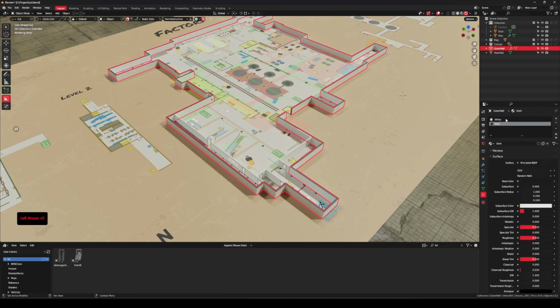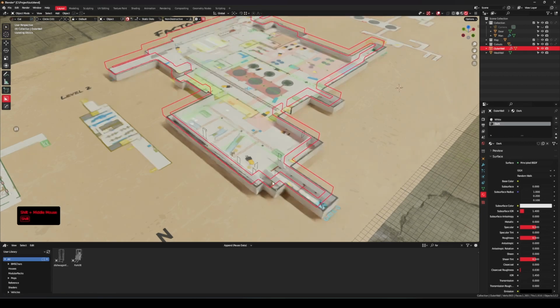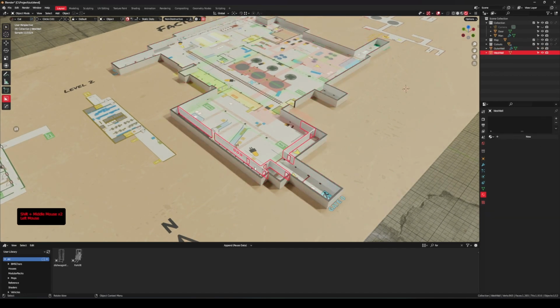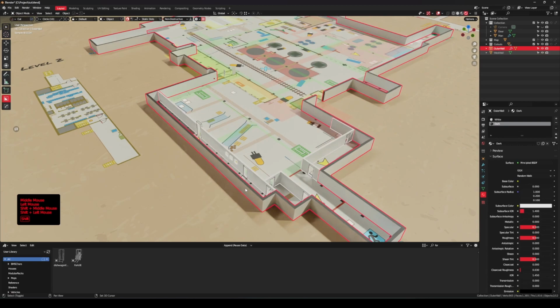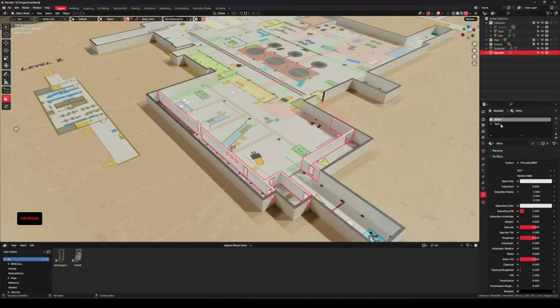And that's because up to down it's 0, then 1, and then 2, and so on if you added more materials. But yeah, so as you can see, this inner wall here doesn't have the same materials. So what we could do is click that inner wall, shift click the outer wall, Control L, and link the materials. Now the inner wall will adopt those same 2 materials.